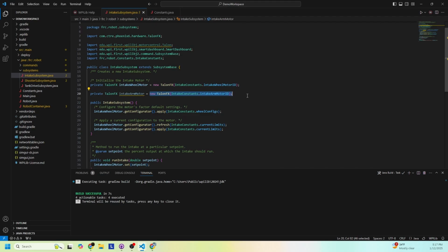That pretty much sets its coordinate system for the rest of the time that your robot is on. You can re-zero and reset this later, but it's important to note what your mechanism's 0 is, so then you can start your robot with that 0 in a consistent position.